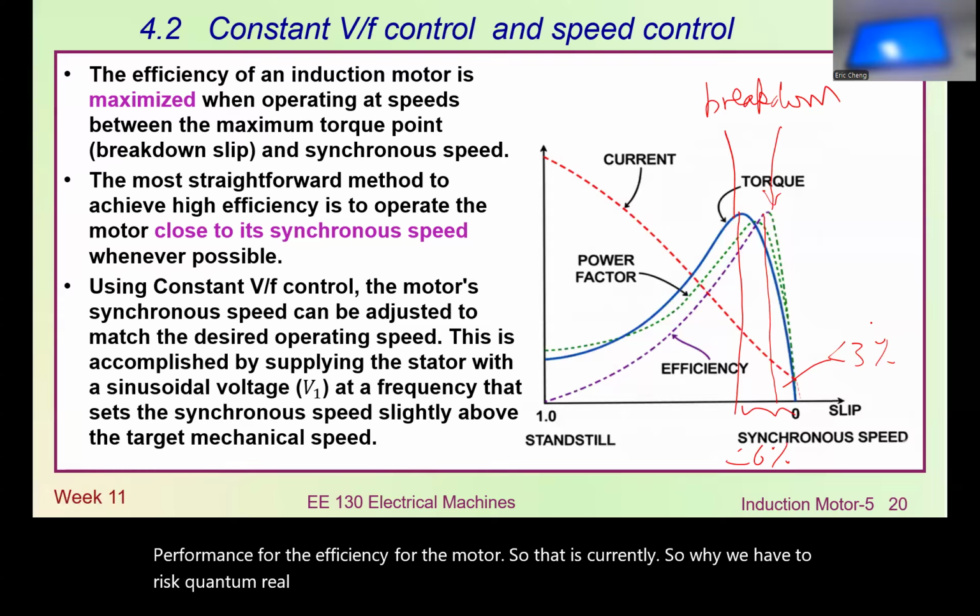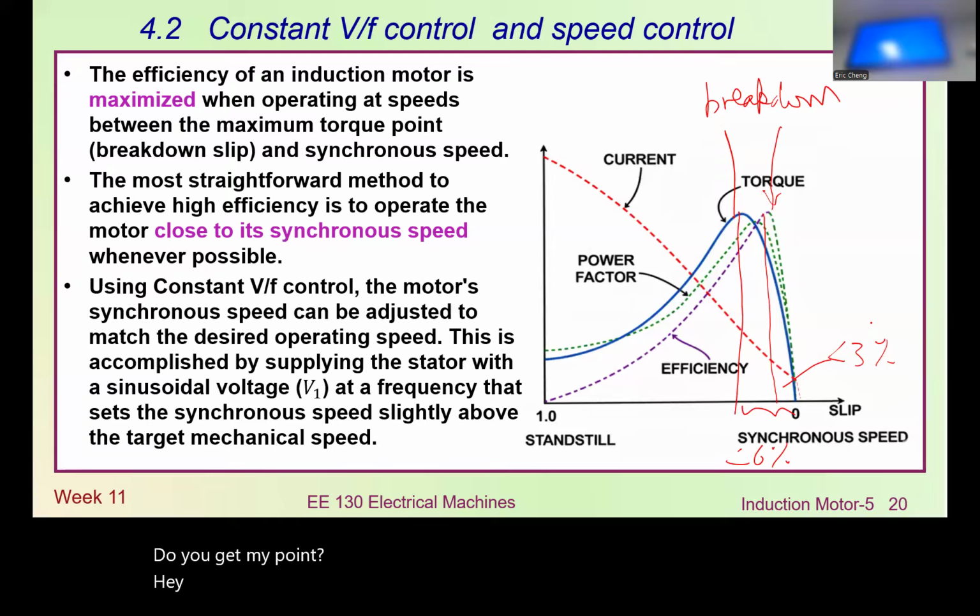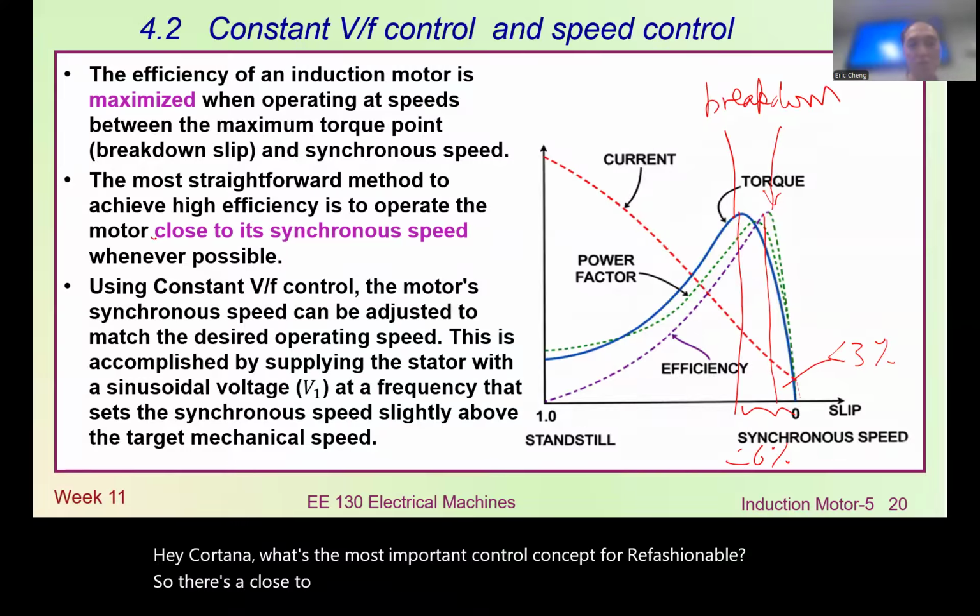When we change the voltage to achieve the frequency, why do we change the frequency? Because we need to make sure that we operate in this region. Do you get my point? Simple enough, right? That's the most important control concept for induction motor. So that's close to the synchronous. That's the most important. It's close to the synchronous.